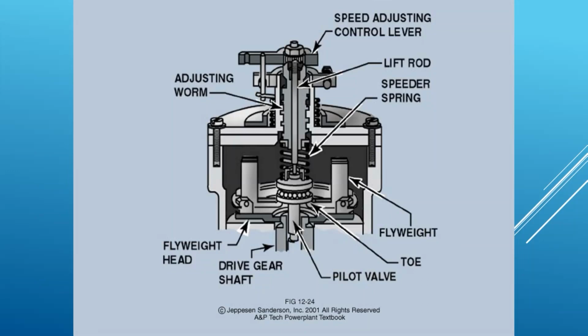But if you push down on this spring, you put more pressure on it, that's going to resist these flyweights being able to spread out, right? If you put less pressure on it, the flyweights are going to be spread out more. And so that's how we tell the prop governor I want more or less RPM on my prop. I allow the flyweights to spring out easier or spring out less easily. And that's going to be opposite again, depending on whether it's designed to port fluid in order to speed the propeller up, or it's designed to cut off fluid to speed it up.